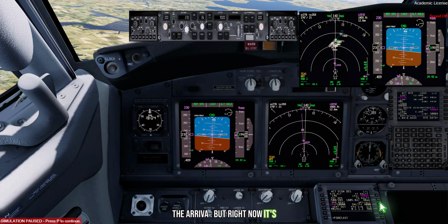But right now, what's important for you to understand is that this vertical bearing that is showing up here, that 1.2, that's telling me that I have to make a descent that has at least that angle on the aircraft. Now, right now, this flight path angle, I'm flying straight and level here. I can see here that I am. So that's what the angle of the airplane is through flight.